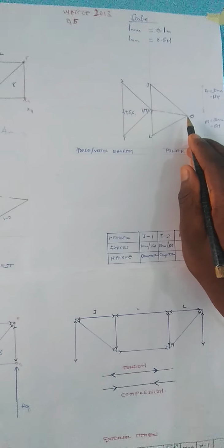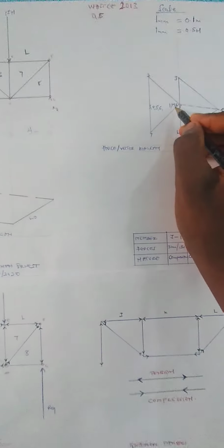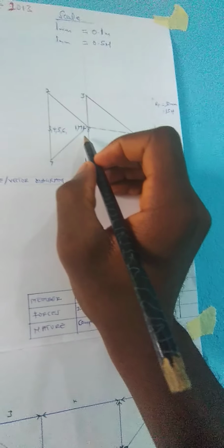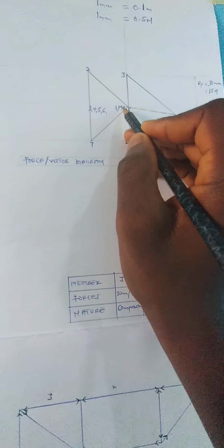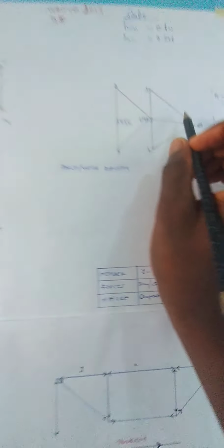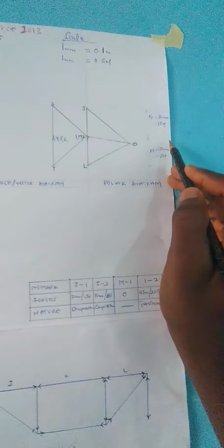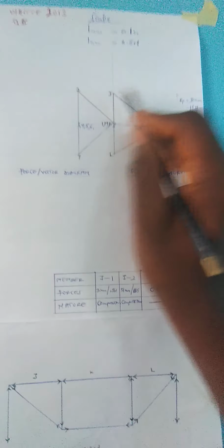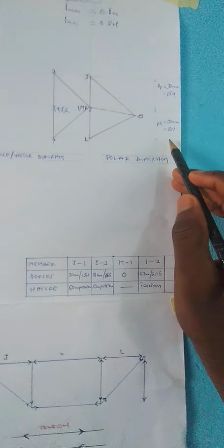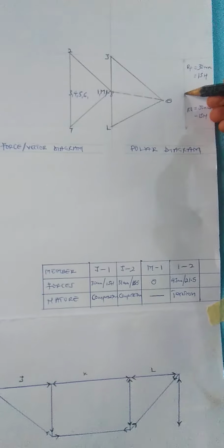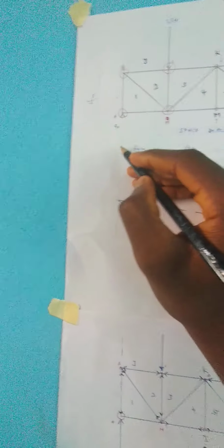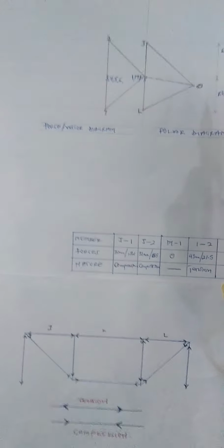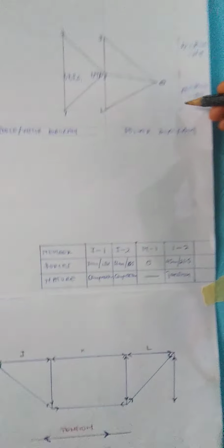So when it lies on the same line with KO, you label it M. So at that point, we are going to have K and M all on the same line. When you transfer this with your T square, you transfer J, you transfer L. From M to J is the reaction RP. And from M to L is your reaction RQ.